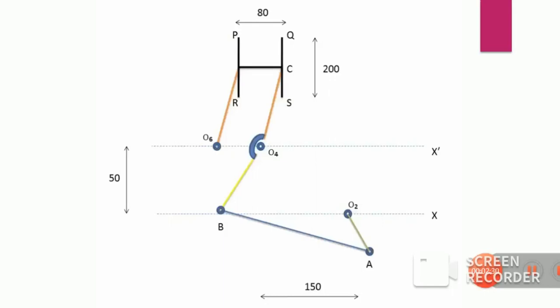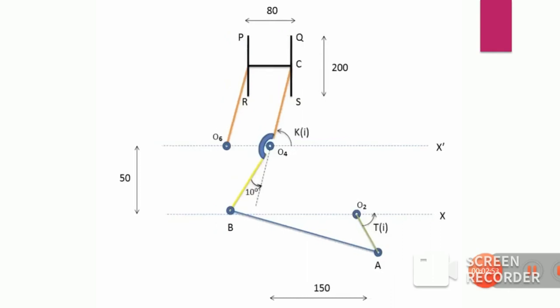In order to know the area swept using the wiper, we should find the locus of points P, Q, R and S on the wiper, and we need to find the variations of coordinates P, Q, R and S as crank O2A rotates about the origin O. We need to know the angle made by the crank O2A.